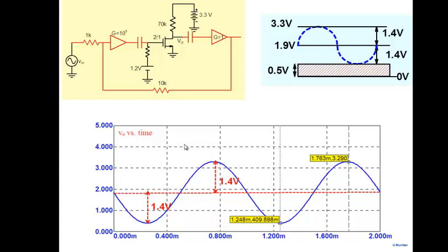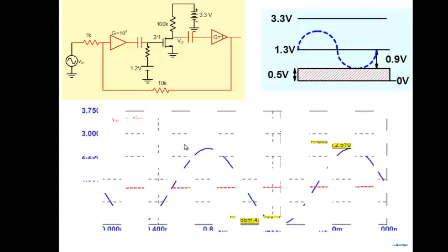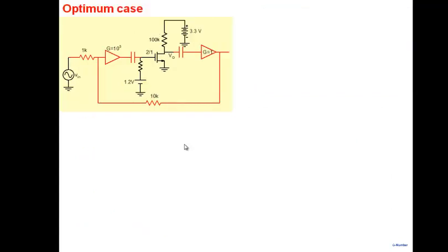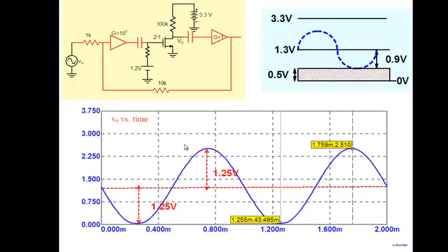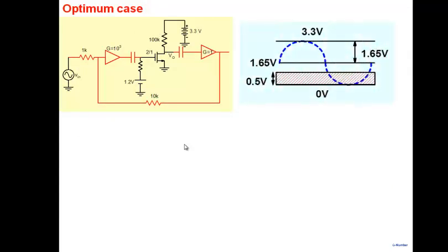But then the issue is, how does negative feedback reduce distortion? What does it do? Earlier, the input sinusoid you were sending would be distorted. Look at that. If I put 1.3, so the point is, the biasing should be, as you can see here, in the middle. If I bias it at 1.3, the swing then is accordingly a problem. Or let me show you here what is happening.